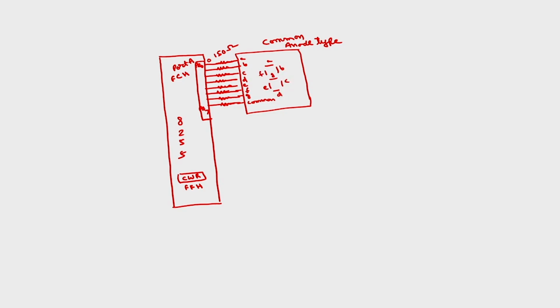This is interfacing. So if I want to implement a decimal counter on this particular 7 segment display, it means first you display 0, then 1, then 2, and so on up to 9, then after 9 you again come back to 0 continuously, and you allow some time between 2 consecutive counts, say 1 millisecond or 1 microsecond, depending upon the application.